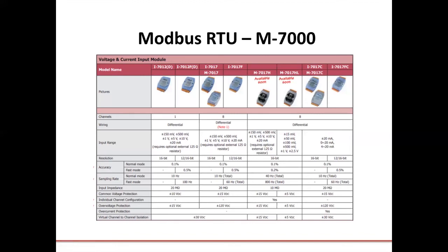Resolution also plays an important aspect of your system. So you want to be sure that you can get the resolution that you need for your system. If, for instance, you need high accuracy or resolution, then you need to pay attention to getting data acquisition hardware which will have the accuracy needed. Because even if the sensor can achieve the accuracy or resolution which you need, the hardware also needs to have that ability. Otherwise, the resolution won't be there in your software.